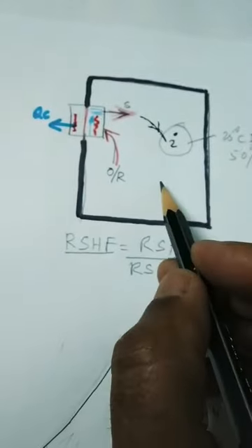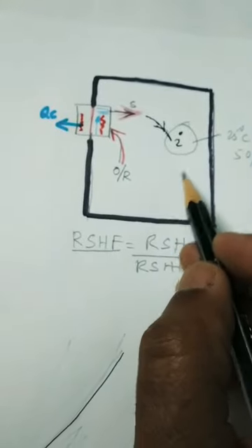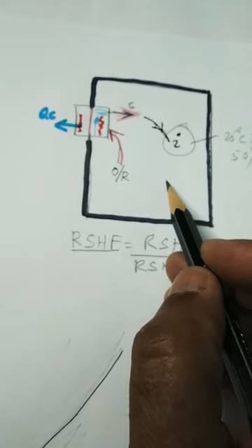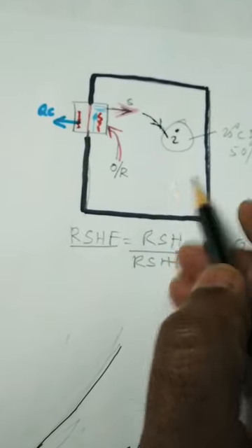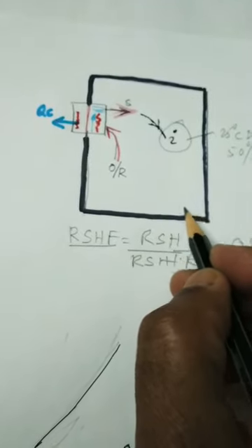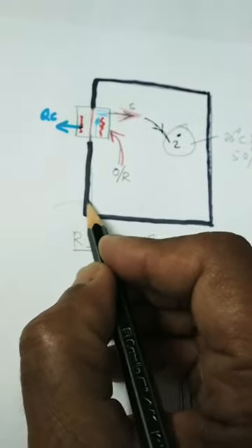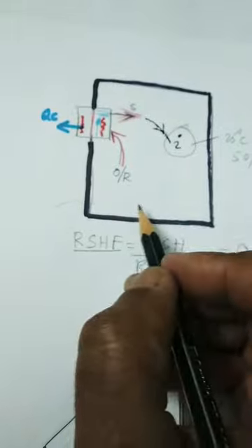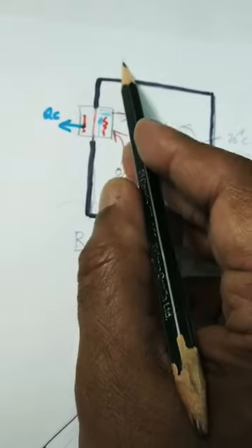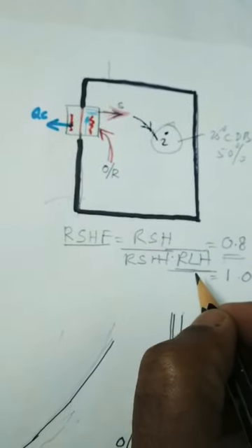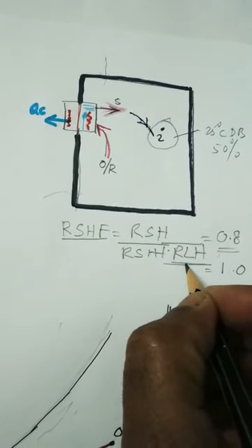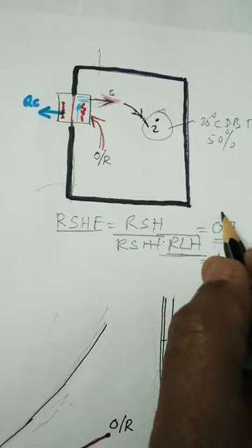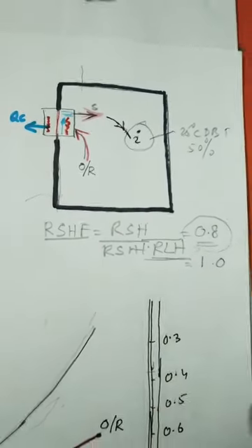Means there is somebody inside this room who is breathing out air containing humidity, and there is something producing steam over here. There is some infiltration from the door, if you see the last lecture, or some fresh air is coming from outside. Because of this contribution there is a certain amount of room latent heat load, because of which room sensible heat factor is coming out to 0.8.